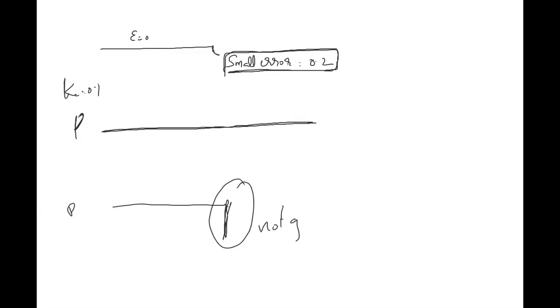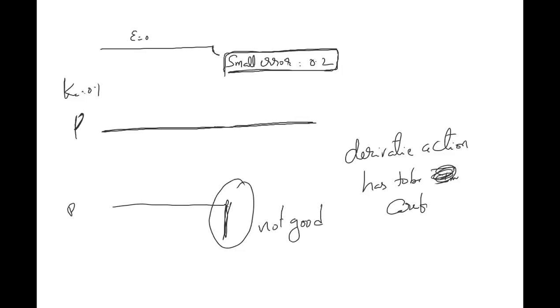This makes a system which is in steady state go into an unsteady state because of the extra action. I'm taking extra action, which is good if there is really a problem. Even if there is no problem, if I take extra action, that means it is not good for the system. That is why this derivative action has to be implemented carefully, because then the system will start reacting to small errors, which are like measurement errors also.